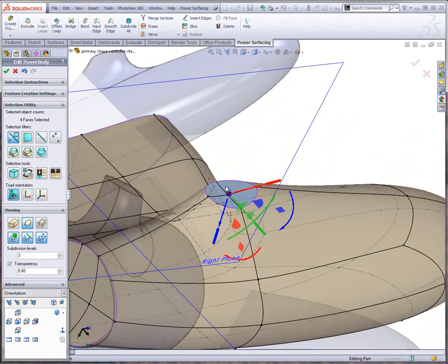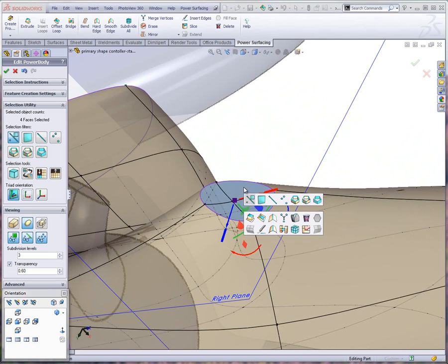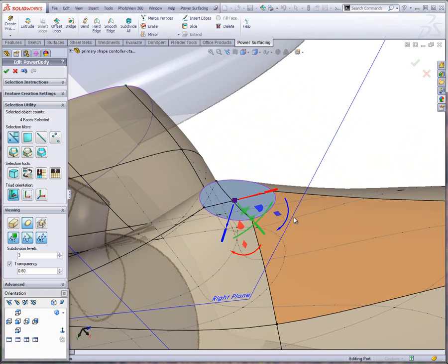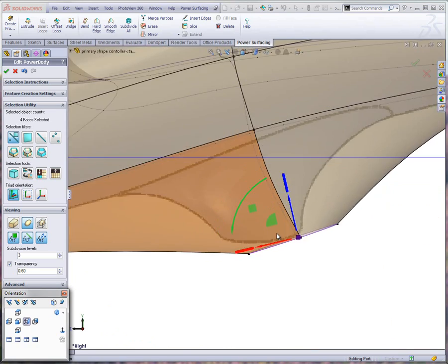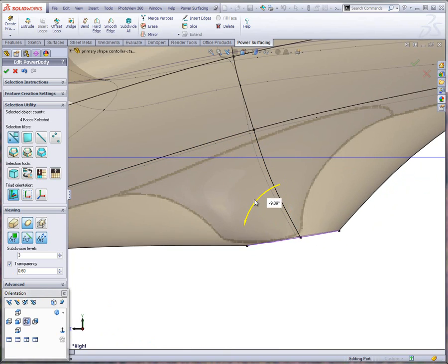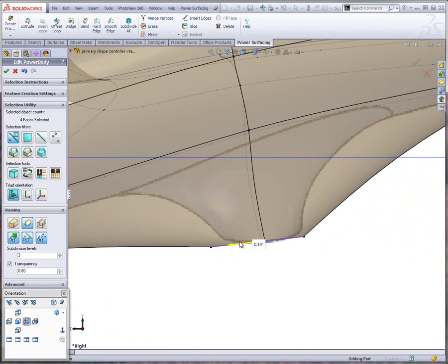And then also while I'm there, I should probably flatten that area. So I'm just going to use a little iron icon to flatten that. And now if I go back to my side view, you see that we have a flat kind of surface there. We can rotate that a bit and move it into position per my sketch picture reference. Maybe scale it down a little bit.